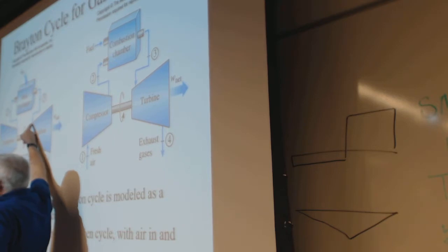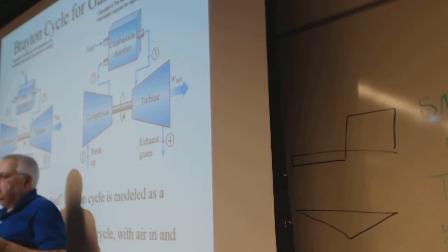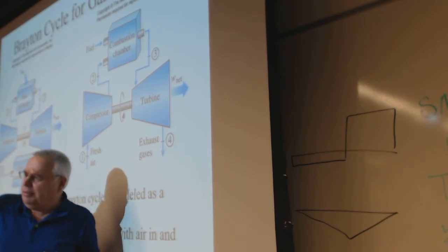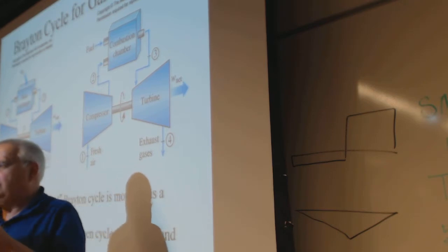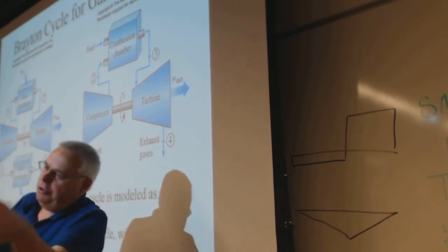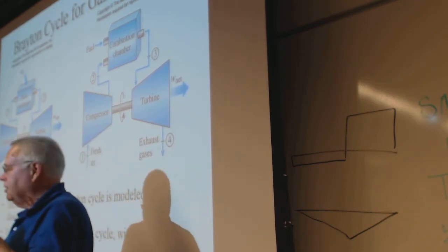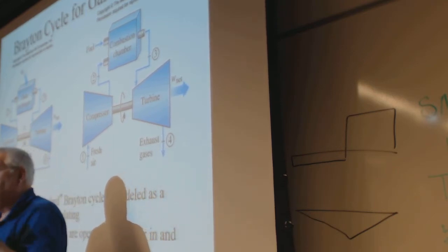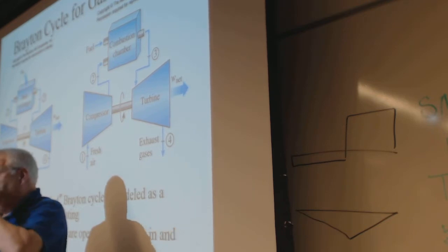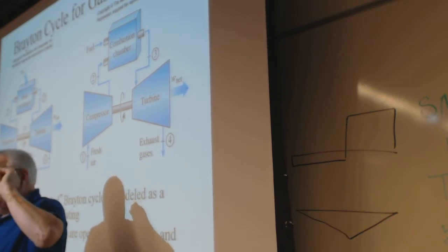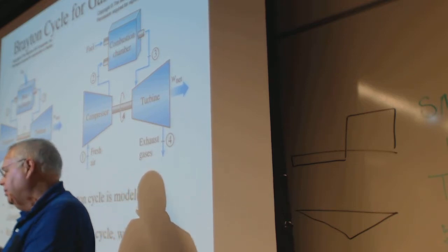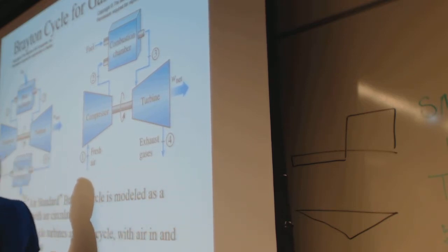And then the turbine takes it and it expands, but what's it really doing? It's coming at high pressure, it goes against the blade and blows it, and the blade turns. What's really going on is an impulse, a mass flow rate, velocity change, direction, force, action, reaction kind of thing inside there.